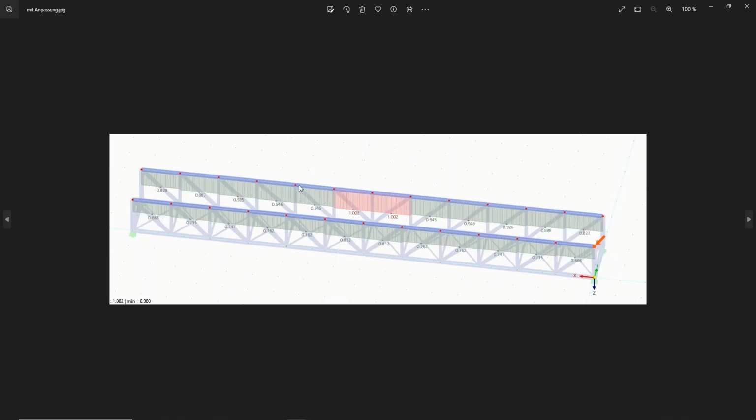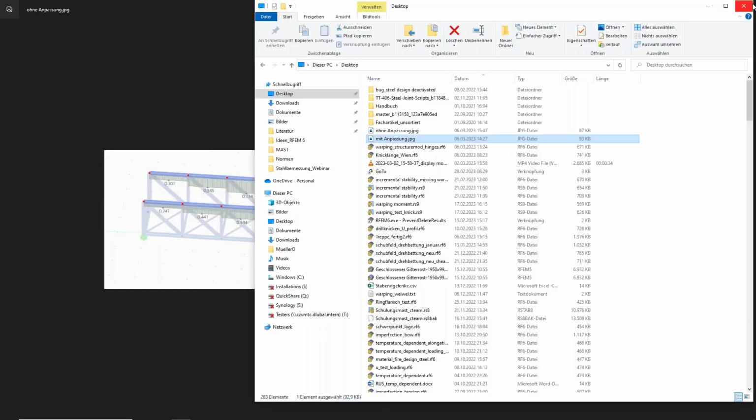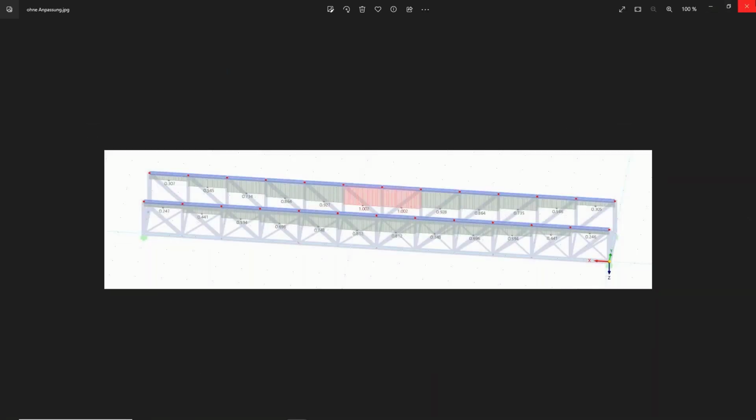If I use always the corresponding buckling length, then it would be a smoother distribution. So now I am a bit on the unsafe side for the outer beams, but as the most governing design check is in the middle, and I use the same cross section for the whole member, which is also the basis for the equivalent member method, it is okay in my case just to use this effective length from the members with the highest compression force. Okay, so now I use it here.